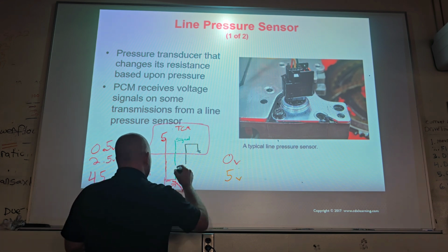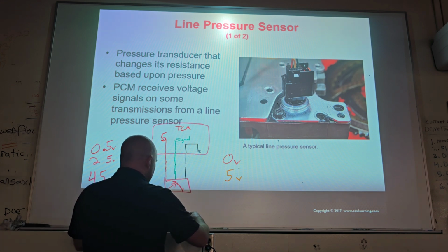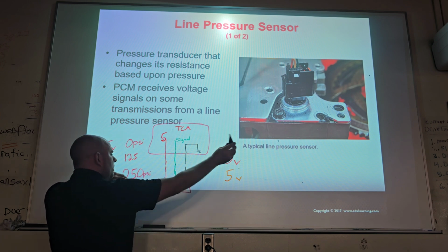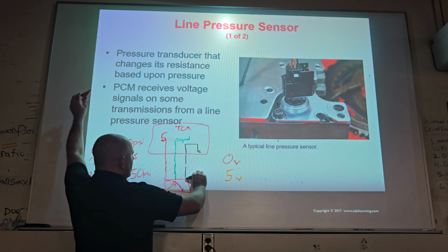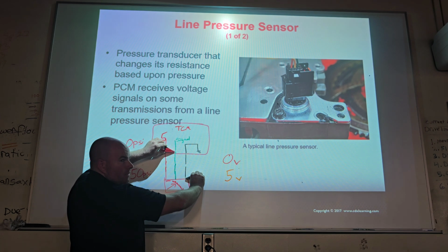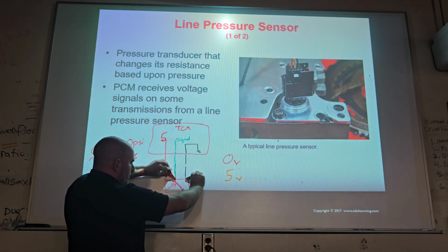However, to really diagnose it, right, make sure you got 5 volts in ground, and then you probably leave this one on ground and come over here and be like, all right, what do I have? Maybe right here you have 2.5. Maybe right here you have 0. Then you'd know it's the wire, right? What if you were to go right here and you had 0? What's wrong?